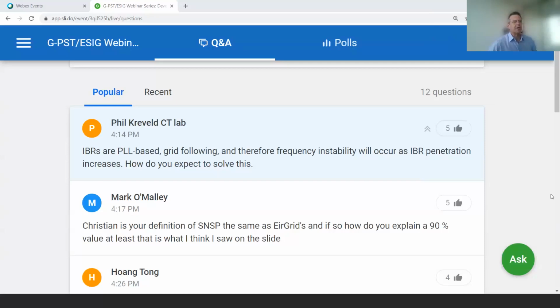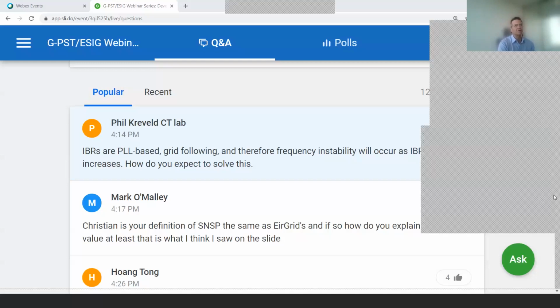That's right. So we had, for security reasons, to dispatch a minimum number of 4 synchronous units in South Australia. By the middle of the year, though, we are planning to commission, or the South Australian system owner or network owner, ElectraNet, will be commissioning 4 synchronous condensers, which will then allow us to review the need for operating that many and potentially reduce the number of synchronous generators we'll need online. So there will be some ongoing changes.